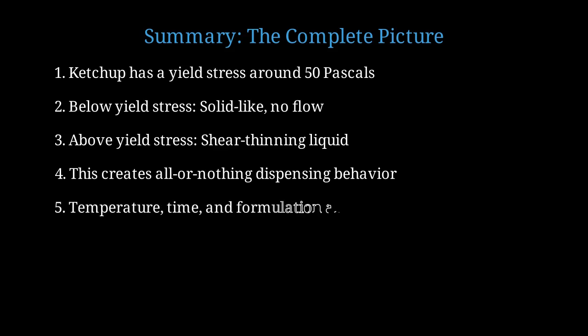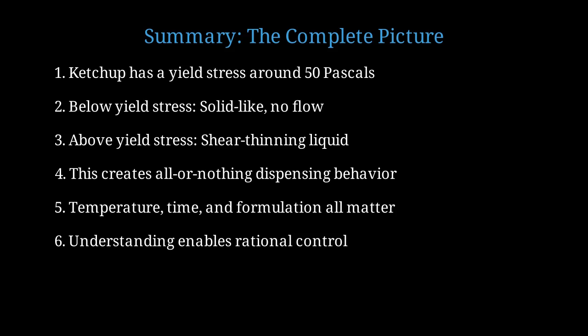Temperature affects molecular mobility, time-dependent thixotropy causes gradual structure breakdown, and formulation determines all quantitative parameters. Understanding these principles enables us to rationally control ketchup's behavior through optimal dispensing techniques and formulation choices. I hope this lecture has given you appreciation for the rich physics hidden in everyday materials.